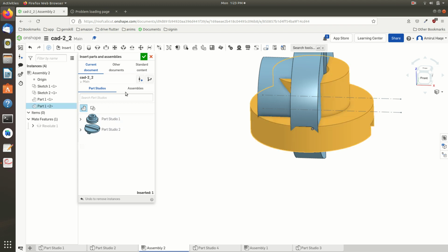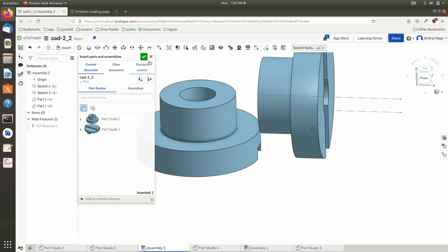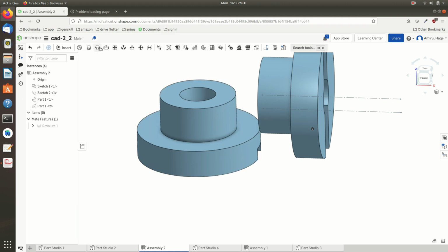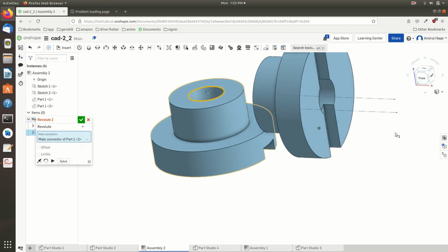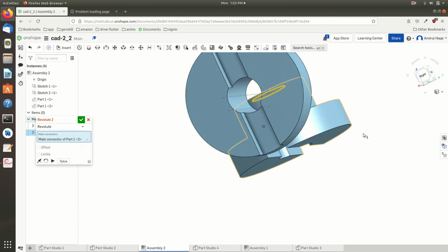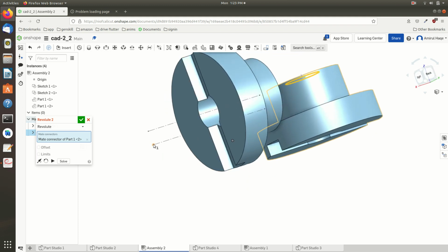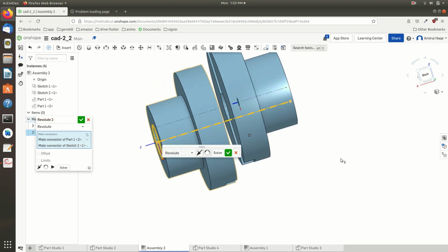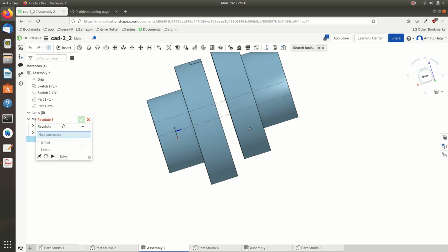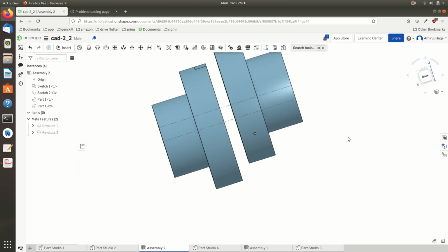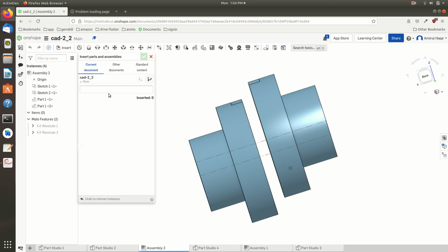And now you can insert one more, or it would be better to create another thing. Now this time again revolute joint, the extremost circle, and you can choose the other axis, you can see it is this one, right? And here this at the end. So that's done, and you can see a gap of 16 millimeter, which is where the disc is to be placed. So now you can import the disc.